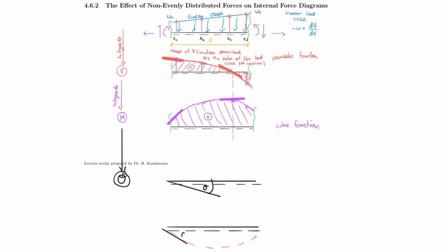So I'm going to mark this one more time for your reference. But what we really want is to know how much this deflects in this direction, right? So this we call delta. And that is something we can find by integrating the slope angle, or what I call theta here.